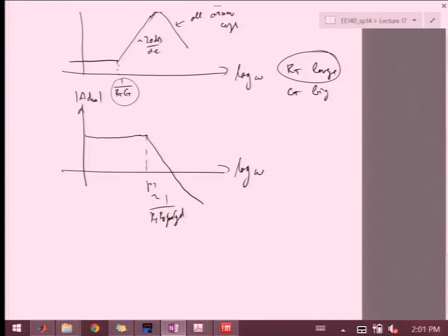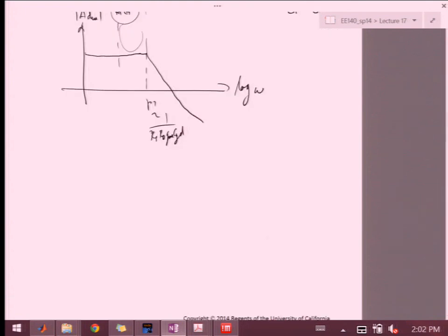So if you look at this region over here between the two, what's happening here is that differential mode is staying constant, common mode is increasing. So what's happening with my common mode rejection ratio? It's going down. And it's still within my bandwidth. So this is where things are still useful for me differentially, but I have more sensitivity to common mode, meaning supply noise, all the other stuff. And unfortunately, supply noise and all these things are all high frequency anyway. So this is actually the region where we start having problems.